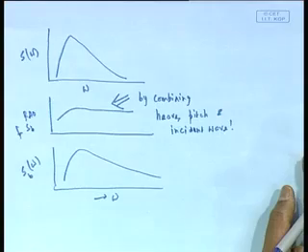Obviously that is important because you see the bow part, if at the same time it goes down and it pitches, obviously it will go down much more. So the phase is very important. That is why when we calculate RAOs, remember that phase becomes equally important because that is very relevant for derived responses. And derived responses are the ones that are more important from the practical point of view, that we would like to know.